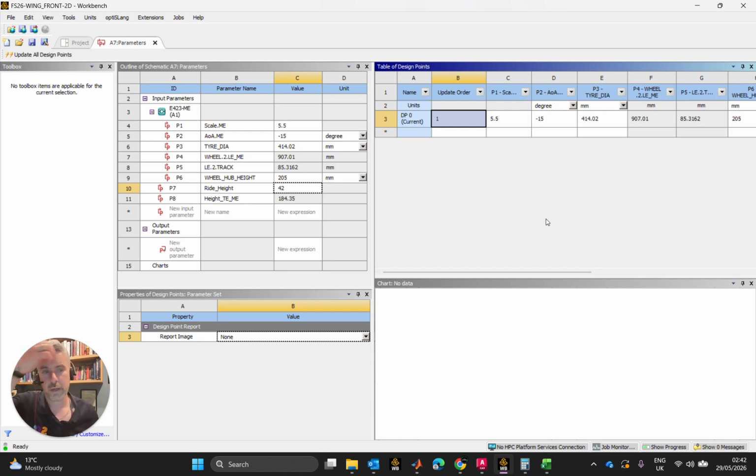There might be some more filtering to do with the parameters after we do the meshing, and certainly whenever we do the solver, the Fluent solver will be outputting lift and drag and L over D and pressure coefficient and those bits. So we'll be able to see how they resolve within this table of design points, and keep developing, see what sort of results we get out of these and how well this workflow will actually turn out to be.